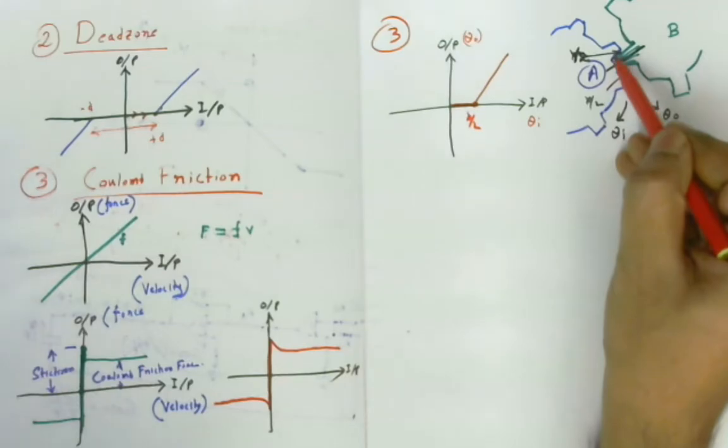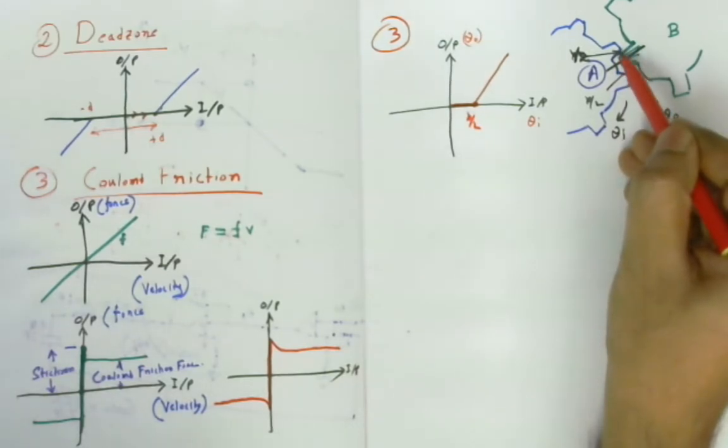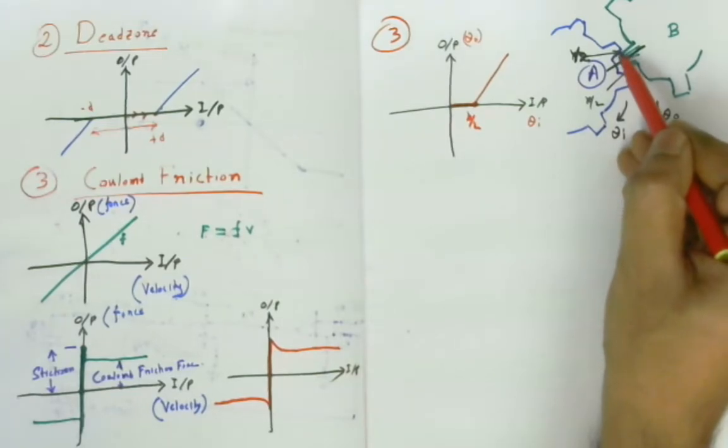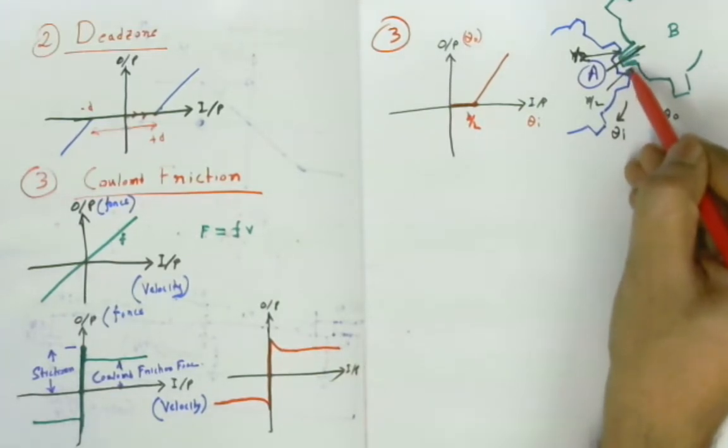when that side of the A teeth touches that side of the B teeth, then this B by 2 gap is no longer there, it has touched. Now if it is touched, then this overall gap becomes B by 2 plus B by 2, which is B.